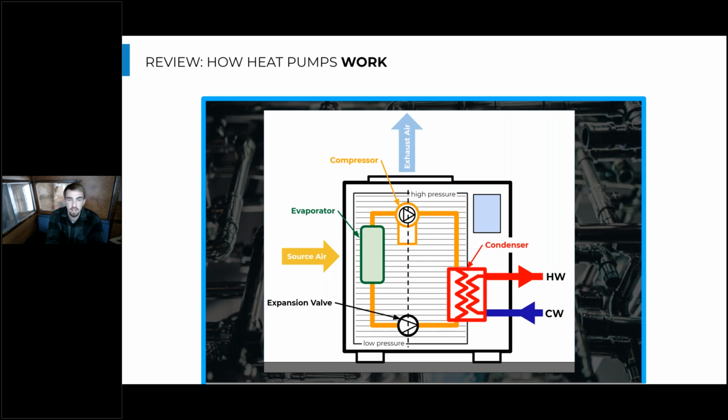And that's the thing we need to focus on when we're thinking about heat pumps in terms of design or maintenance, is they're really designed to move heat rather than create it. And that's why they work so efficiently, is because they're harvesting that heat from the air and transferring that into the water rather than creating that heat through electric resistance or the burning of fossil fuels.